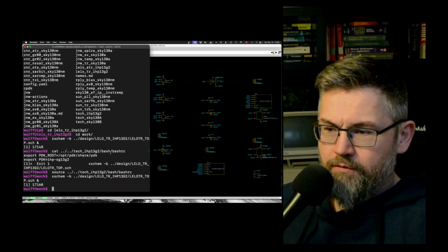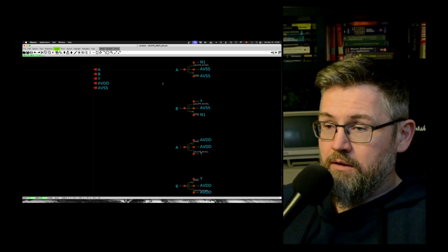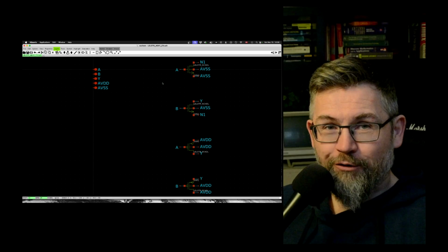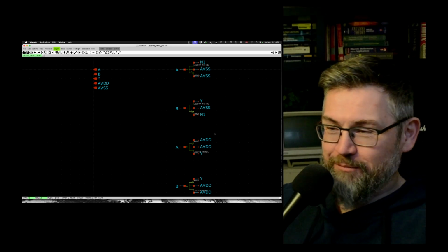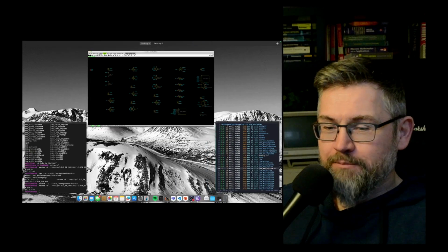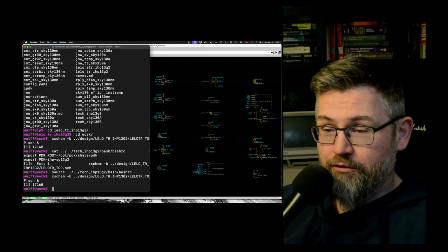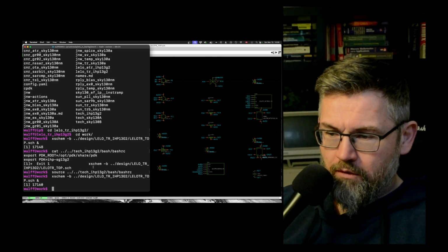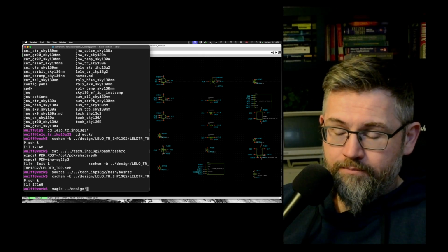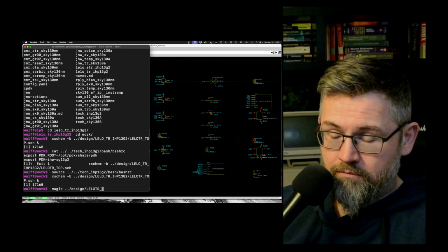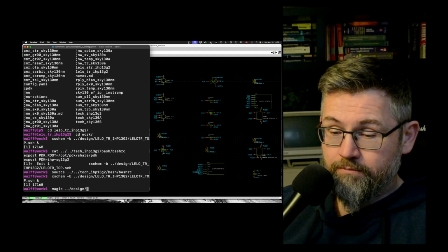So all of this library is, if we look at the schematics for, let's pick the NANDs, you can see that the schematics are not drawn by a human. I mean, it's wrong, right? The PMOSs are on the bottom and the NMOS is on top. That's because this whole library is made by the CIC Creator and the transpiler afterwards. But before we run that, let's look at the layout. Top. No, I need the library first.